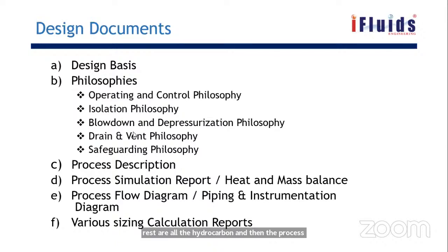And similarly, all the process gas will be vented through a closed venting system, where it will finally be vented safely through the flare system. And any steam system can be openly vented.